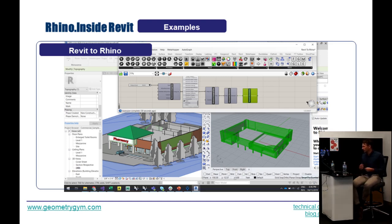So you can filter out elements, get their geometry, and then bake that directly into Rhino. You can bake that to whatever layer you want. You can set up a script that will bake it to your certain layers, so you're not exporting straight from Revit and then having to manipulate that geometry down the line. So I think that's pretty cool.